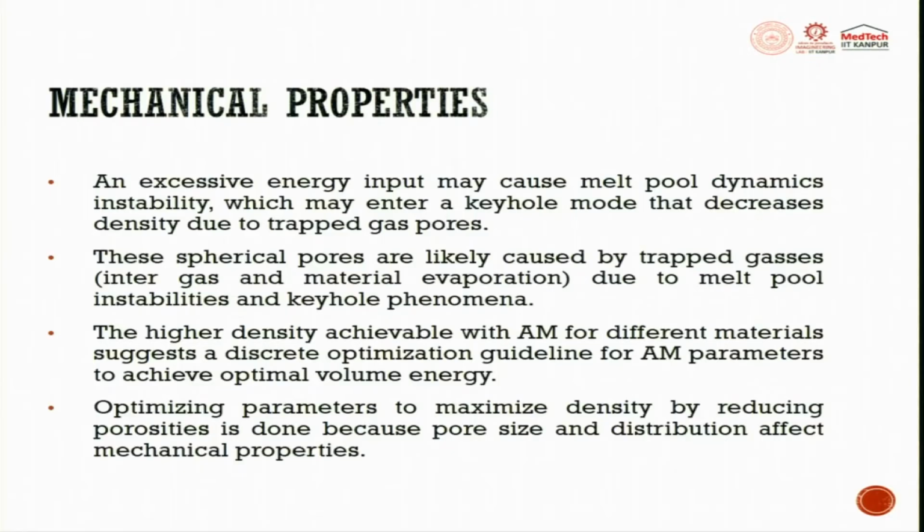An excessive energy input may cause melt pool dynamics to become unstable, which may enter a keyhole mode that decreases density due to trapped gas pores.